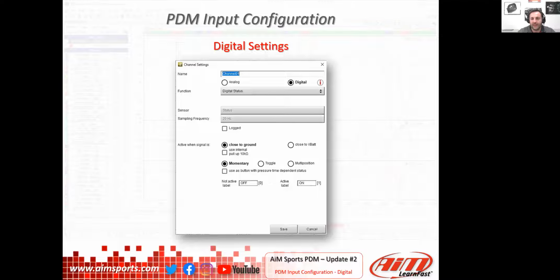So the input could work as a momentary, active when the user presses the button or the external signal is active; toggle, so we need 2 movements of the user to change the status of the input; or multi-position. So also directly in the PDM, we can manage a situation like before, where we can change the output status of one or many outputs, depending on the value that the input has with a multi-position system.